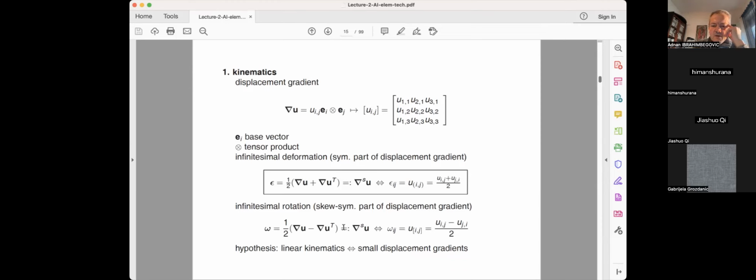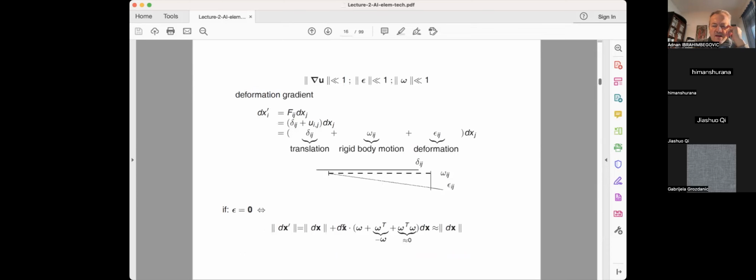We cannot get rid of that, but we don't need it. The idea is that all these values I mentioned, talking about small displacement gradient theory, are very, very much smaller than 1. So if I now imagine the configuration where the infinitesimal vector dx with components dxj is multiplied by something called the deformation gradient, which is identity plus displacement gradient, we'll see when we go to large deformation why this deformation gradient plays an important role.